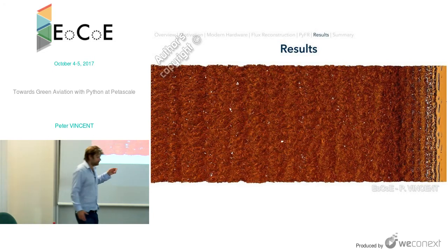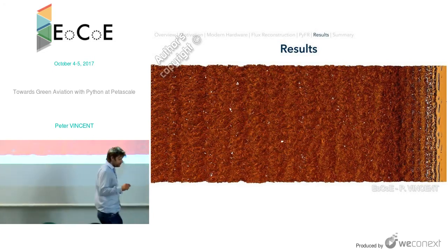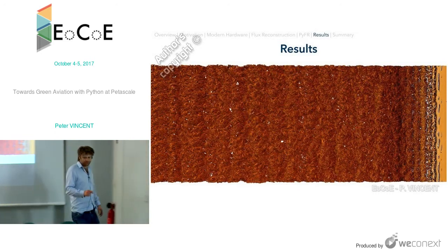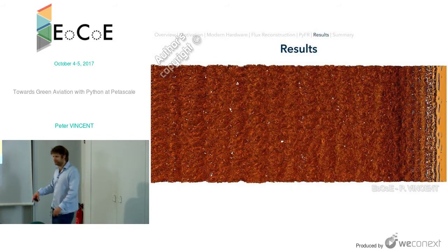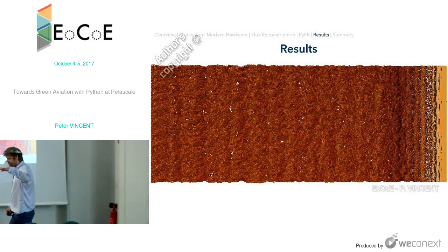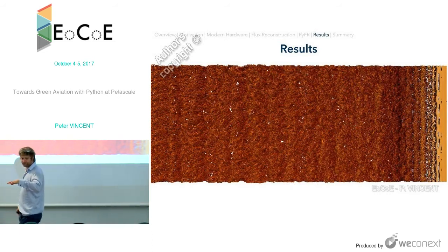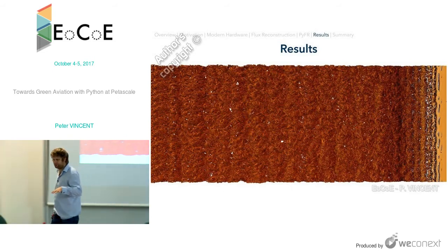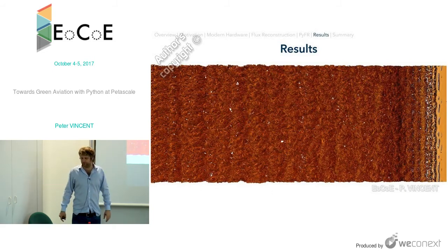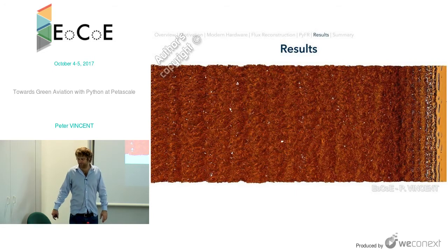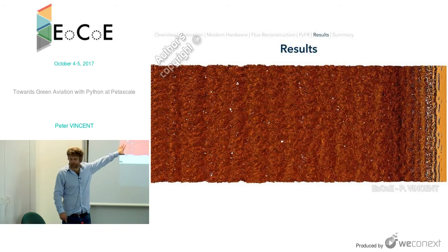So the way we made these animations is we developed a whole in situ visualization stack in collaboration with ParaView and NVIDIA that plugs into PyFR. You've got the solution state in the GPU memory live as it's running. Then live as it's running, it takes that data, processes it with whichever filters you need, does all of the rendering, and spits out a PNG image that's a few megabytes per rank. It composites them together across all of the ranks and writes them to disk.